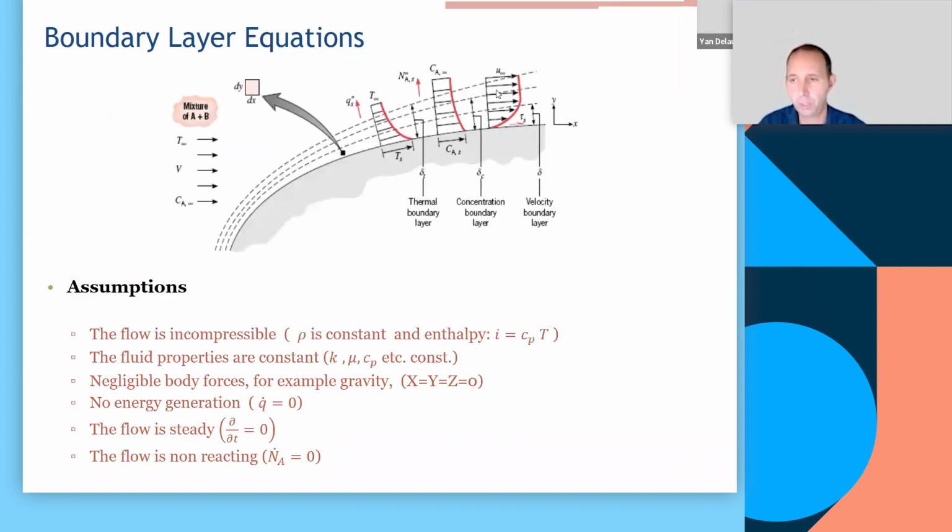If we go back to the sketch representation, the reason why these lines diverge, if they were virtual boundaries of the flow, or if they were path lines followed by the particles, is simply that the flow does move away from the surface here a little bit.